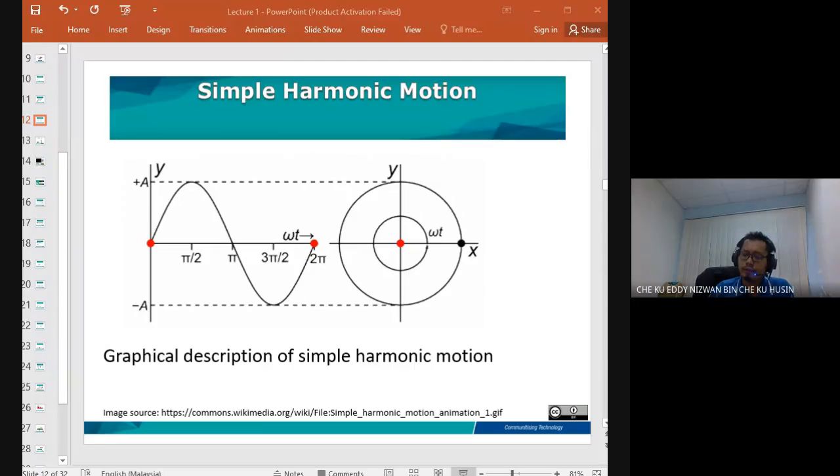Velocity normally comes from integration or differentiation. Displacement normally uses a proximity probe, an eddy current probe, or something like an LVDT. Acceleration is commonly used in industrial applications, which you can acquire using an accelerometer.